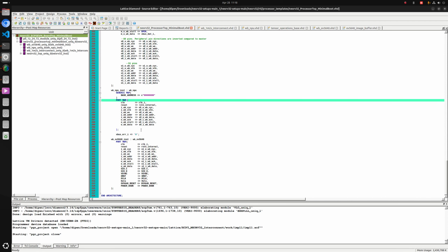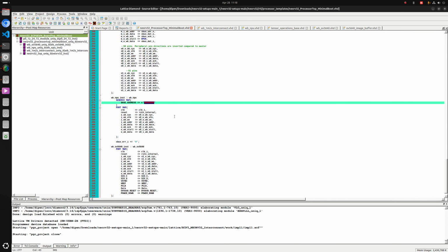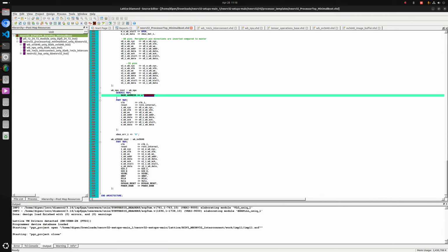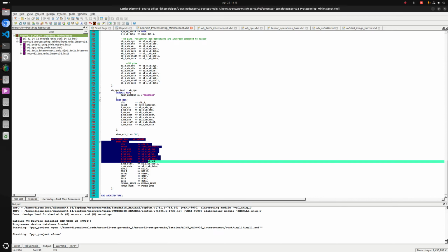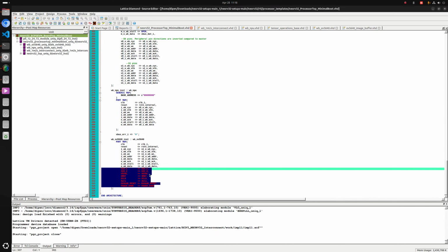The camera controller and the NPU are just simple instantiations. Nothing has been modified by generic map, as you can see; this is just to show it can be done. But please note for the camera controller that this is how we pass the physical pins from the ECP5 board to the camera controller, which is instantiated under the NEORV32.